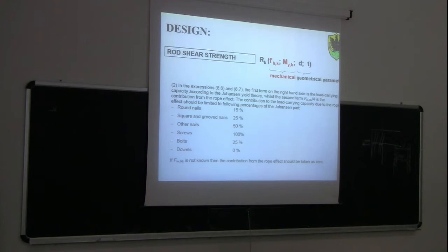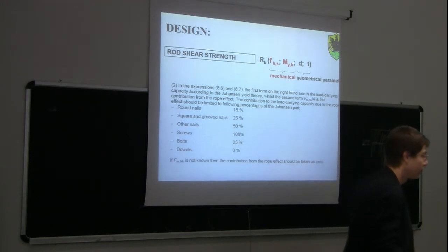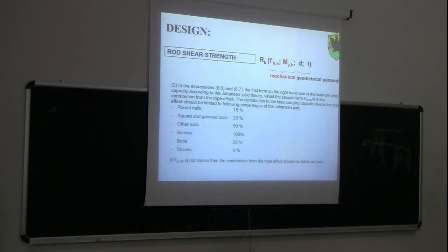Now, in terms of withdrawal strength, so axial capacity, what do you think? Which one of those is closer to a glued-in rod? Since the rod is glued, we can expect that it will have a quite significant withdrawal capacity. For this reason, I would say that the closest one is the one for screws, because the screw, because of the thread, has a continuous bond with the wood.